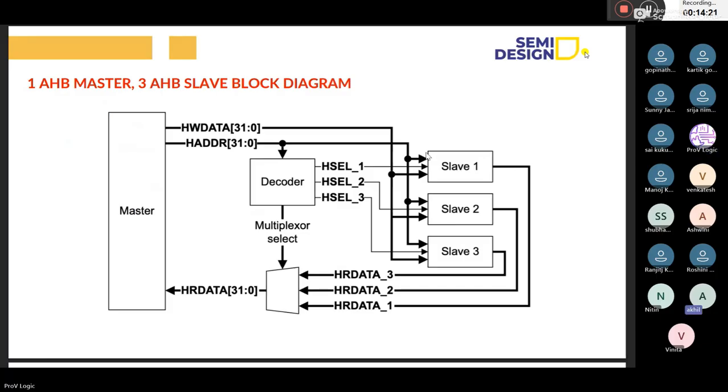Hi, ma'am. So Akhil this end. I have a doubt: if an SoC has APB, AXI and AHB, for all this conversion, do we need to use a separate bridge? Every time you are working, there will be a bridge associated with every protocol. If I want to convert AXI to APB, there will be a bridge, or AXI to AHB, there will be another bridge. So everywhere it will be like that. There is a common bridge module which will be converting this AXI to the corresponding lower power or lower end protocols.